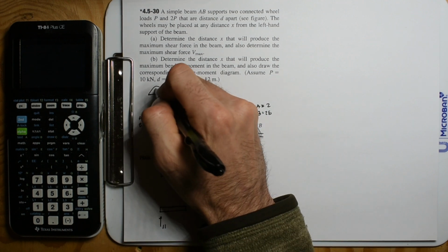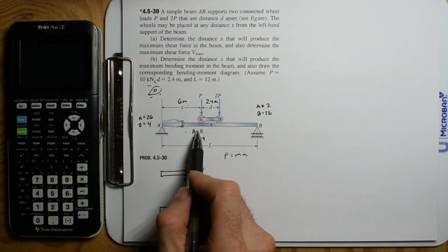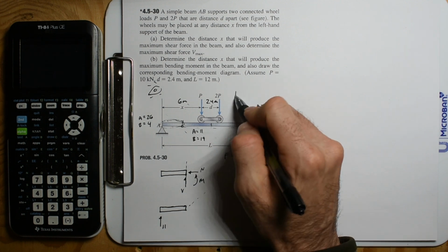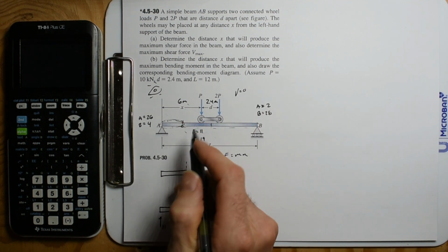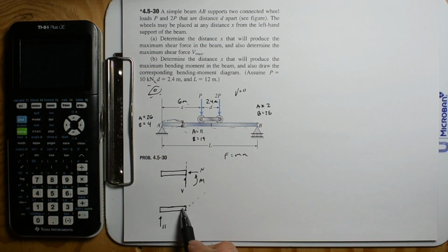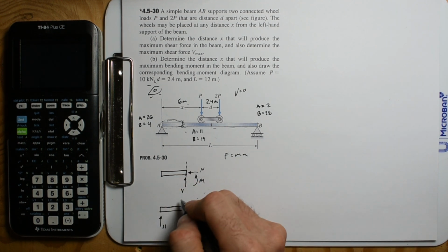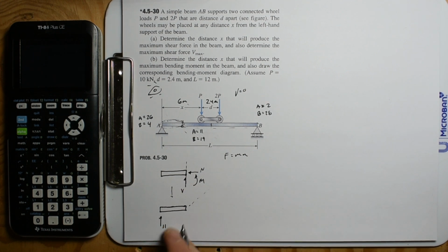But then when we go back down to Earth, it doesn't matter if we chop this whole beam out, everything, nothing's moving on this. So whatever we chop out, it's going to have 0 velocity. So we chop this out. It must mean that the forces must balance. So somewhere we must have a downward force of 11.